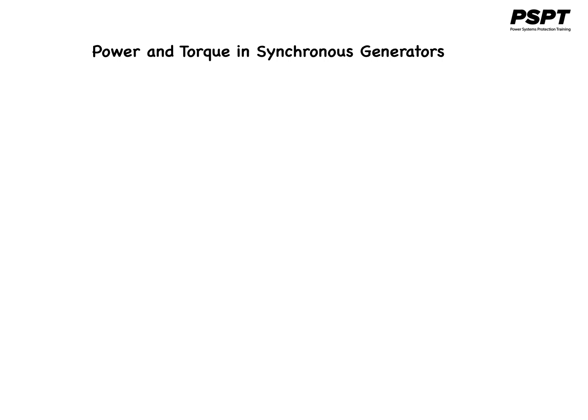A synchronous generator converts mechanical power to three-phase electrical power. The source of mechanical power, the prime mover, may be a diesel engine or a steam turbine or water turbine or any similar device. Whatever the source, it must have the basic property that its speed is almost constant regardless of the power demand. If that were not so, then the resulting power system frequency would wander all over the place. Not all the mechanical power going into a synchronous generator becomes electrical power out of the machine.